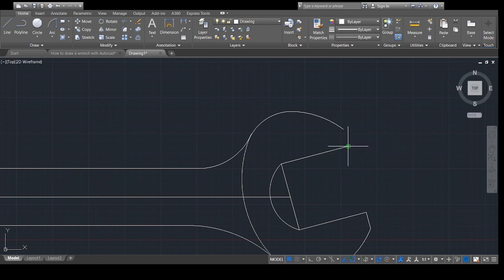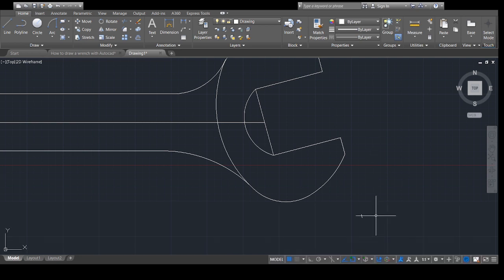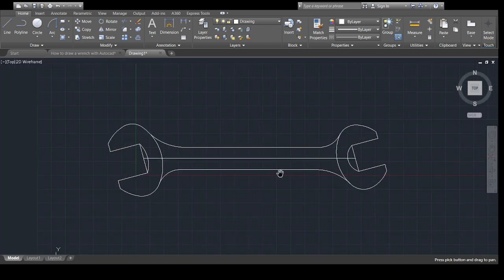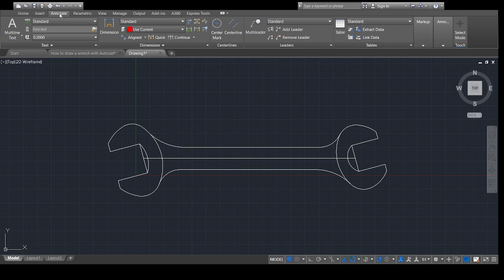Let me fill that up. Alright. Okay. So after putting the dimensions, we are going to delete the other part. So change the layer to the dimension layer. Go to annotate. Then select. Let's start with the linear dimensions. Linear. So you have this distance here up to this point, being 188.